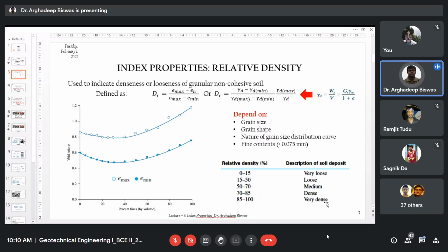Practically, even if you are conducting a similar experiment in labs, beyond 90% or even beyond 85% sometimes, making the soil dense is very difficult. When the compaction chapter is dealt with, this topic will be discussed regarding compaction effort. It is not that you keep rolling that particular surface, rolling and rolling, and expect to achieve greater density. It won't happen. After some compaction effort, you can expect the density achievement to have a reversal.